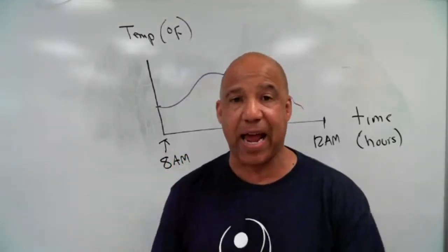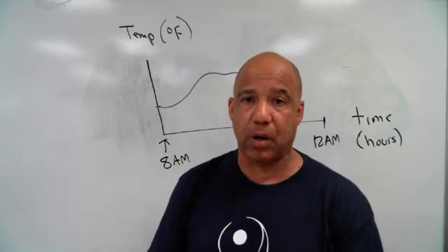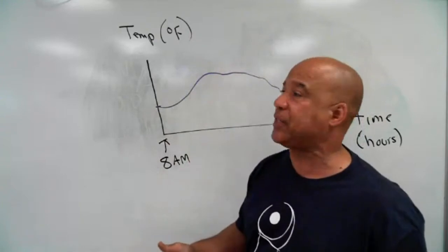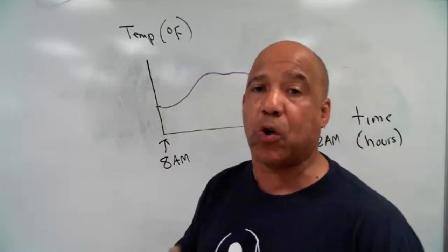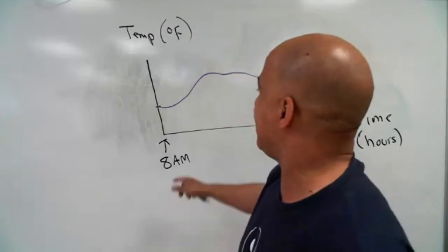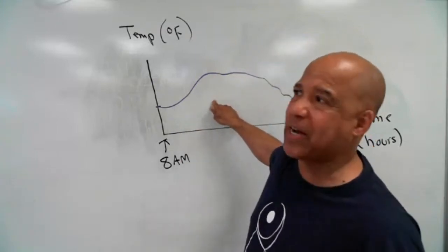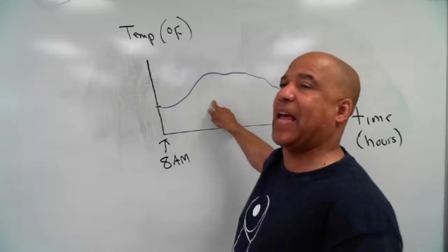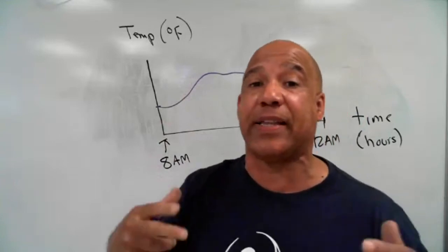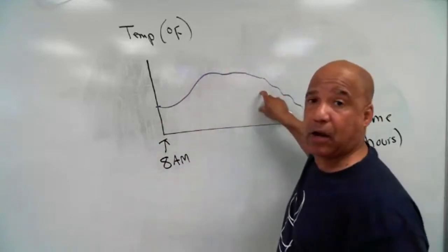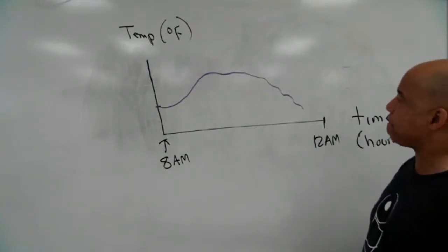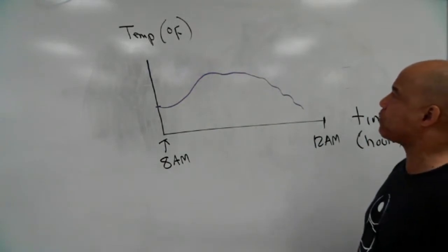If you think of sound, that's analog. If you think of pressure, typically it's analog. Definitely time and temperature, these are analog quantities. And it's safe to say that most quantities we will measure or use as an input for a PLC are going to be analog in nature. Not all, because maybe we want to know if something's there or not there. In that case, it's not analog. But most of the physical quantities we measure in nature are themselves analog. So this will be an example of an analog signal.